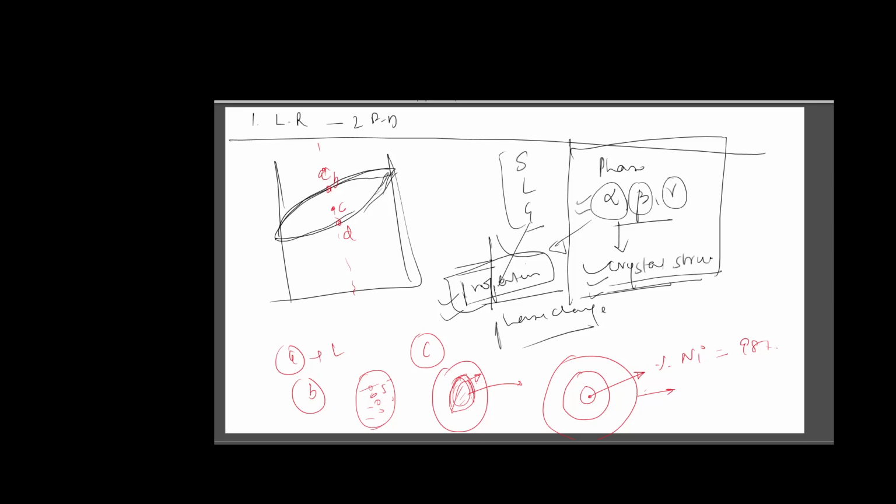We will be explaining why and how this happens. And then when these solidification fronts fuse at D, they act as grain boundaries. So this one arrangement is a grain, and these boundaries are called grain boundaries. And then there is theta, which is the mismatch angle.